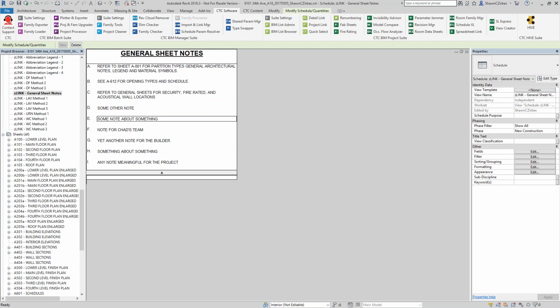I know SharePoint works with this, but if ProjectWise has a link to Windows and you can browse to it natively, then yes, you can browse to it through Schedule Excel, find the file that you want to link, as long as it's some kind of spreadsheet type file, and you can link that directly into the Revit environment. So certainly you could do that.